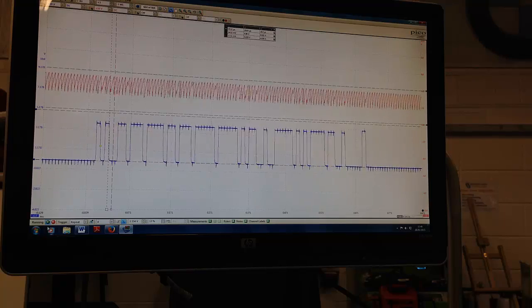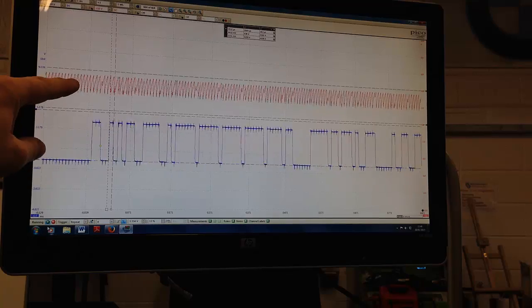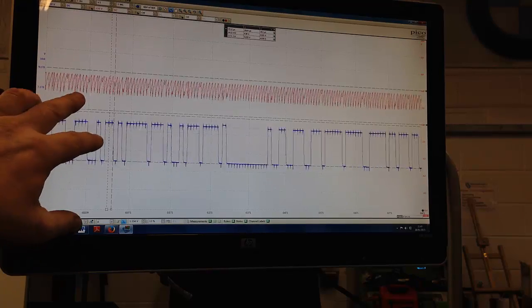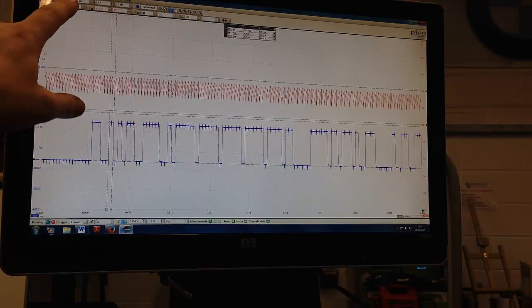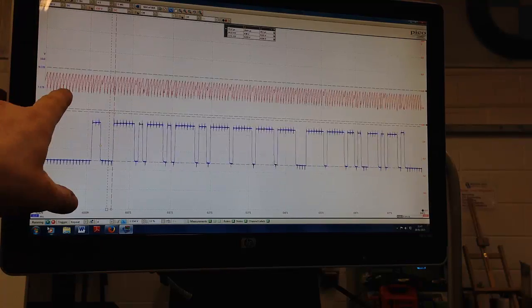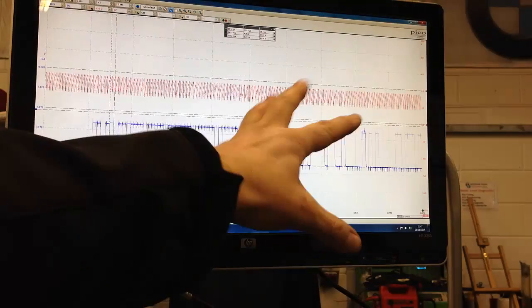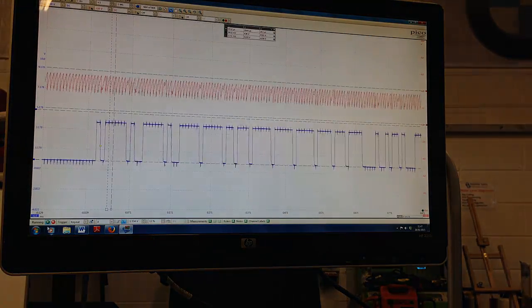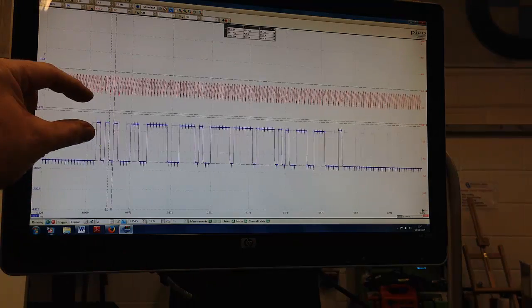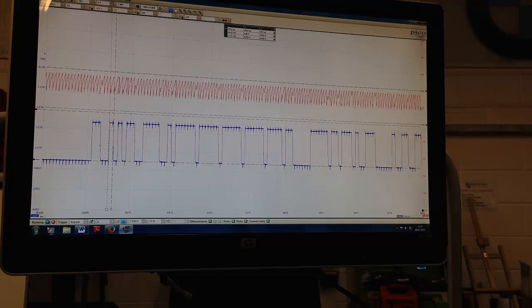Okay, so we've been back to the car now, we've plugged the connector in, and what we can see between the difference between this high and this low now, we've still got the trigger set in, we're still zoomed in at 1 millisecond to watch the individual bit width, but what you'll notice is the top signal has now got some element of disruption on it. The bottom signal has become hairy, we can see these bits of interference, but the top signal is completely unrecognizable.